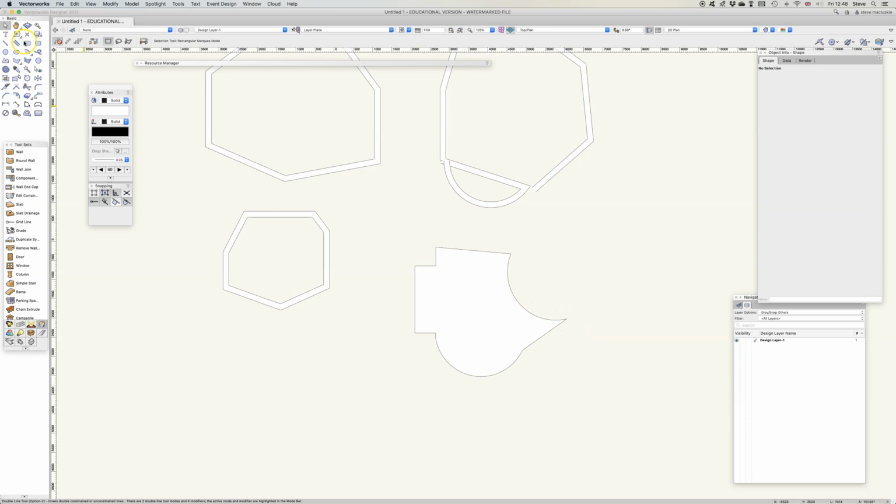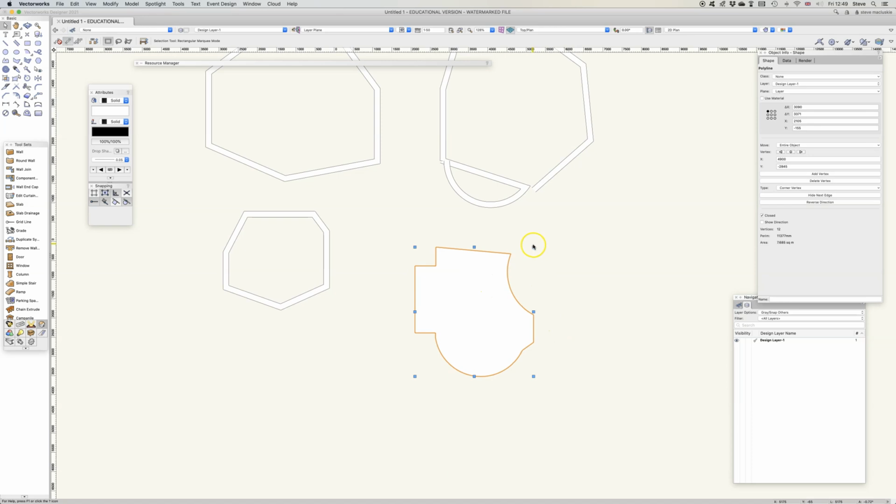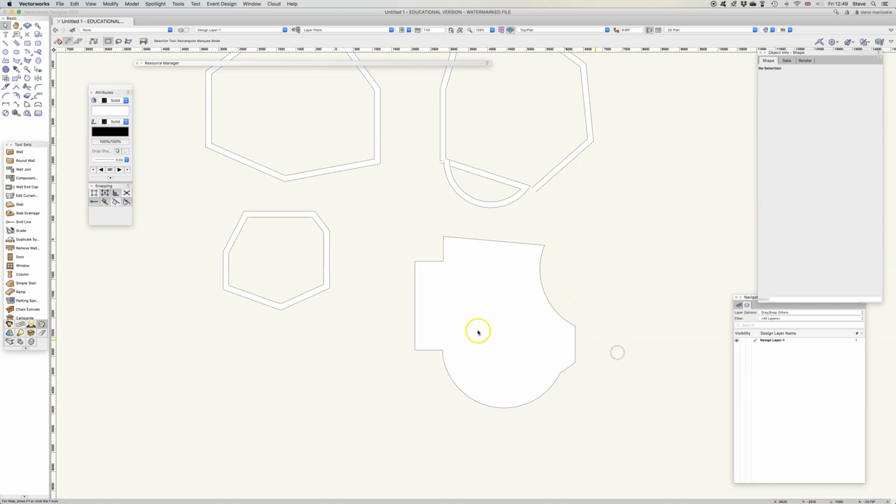That's not going to work as a wall, so I'm going to chop out another little bit there. You should really plan these things rather than just clip surface, rather than just going there. That probably will work. Anyway, that's quite a complicated shape. If you were drawing that with the wall tool, I'm sure you can see how that would be very difficult. Other good things about this is we can change sizes, and squash it in a bit, squash it out a bit. Much easier to manipulate the shape using the 2D polyline tool and add and clip surfaces.